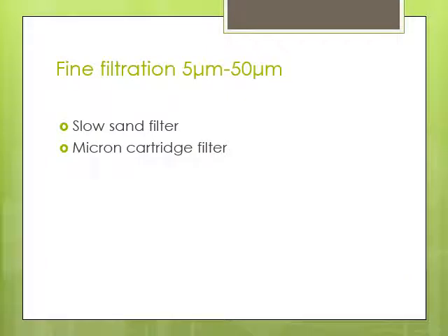Fine filtration. So let's look at the finer steps. That's 5 to 50 microns. Not a lot of farms do super fine filtration. It's not really that critical, but some do need to. Maybe propagators where they're using high pressure fog and the nozzles plug easily.